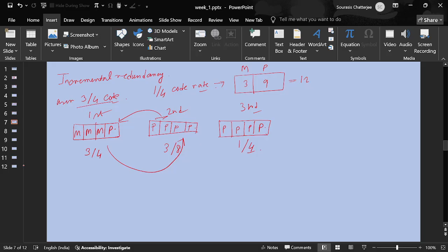Yeah, for example in LDPC, you put more emphasis on the message bits, which are also termed systematic bits, as we have pointed out earlier. So they carry more importance. So that's true, in this case order matters. But for certain codes where the redundancy versions are equal, it doesn't really matter which one you transmit first or second. But here it does matter.